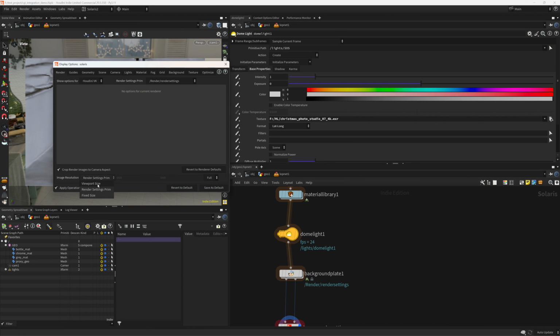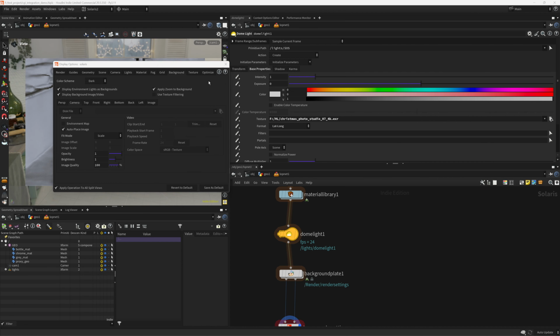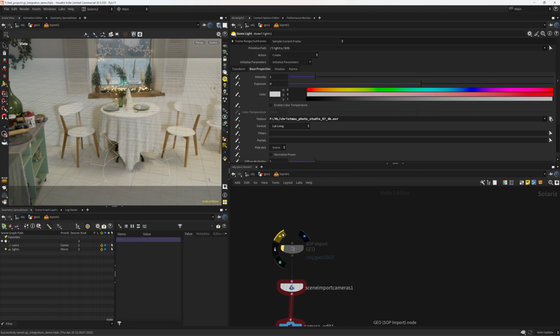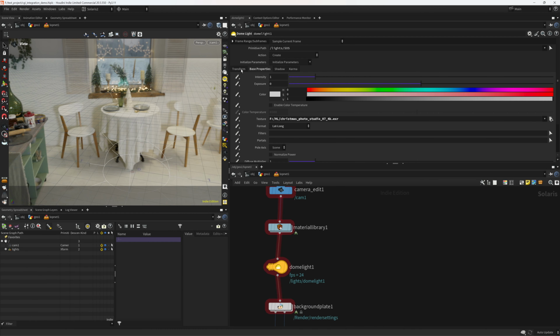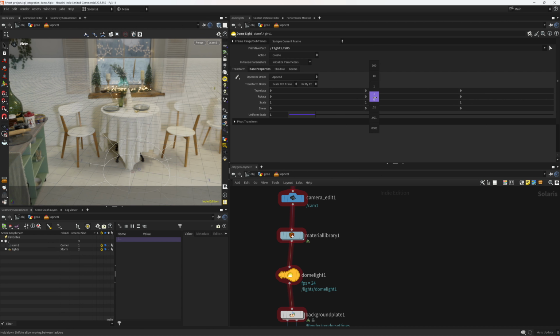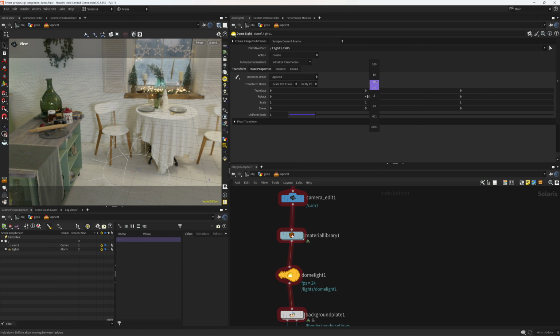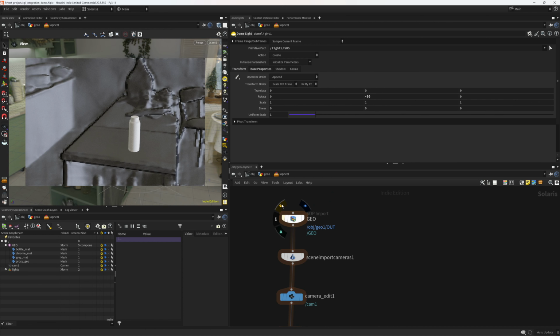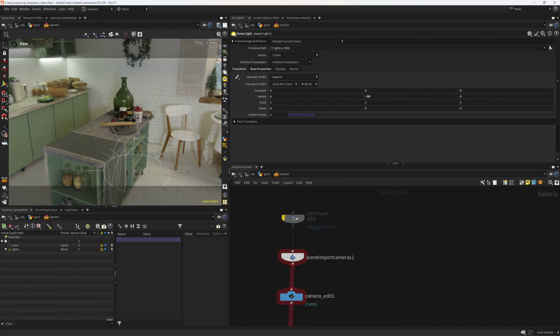I'm gonna make sure I render only the viewport side and change this to dark. I can change this to light, that's fine. Now we need to align this HDRI with our environment. As you can see, it's not properly aligned. This will never be perfect. So I need to change this in here. So for that, I'm gonna rotate this by about, let's say 20, 30, let's see. And that should be better. I'm looking in here. That should be better.